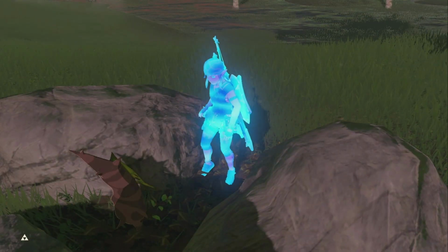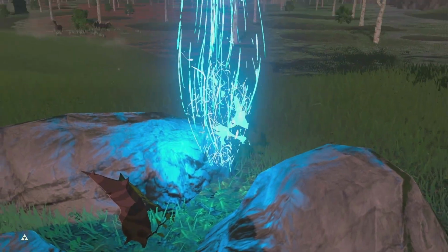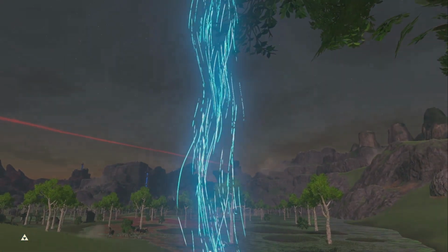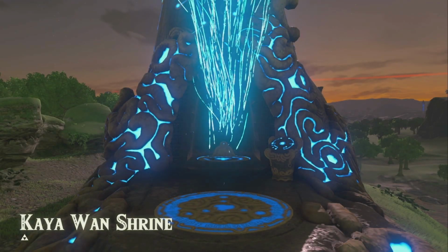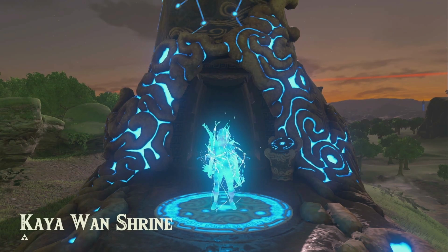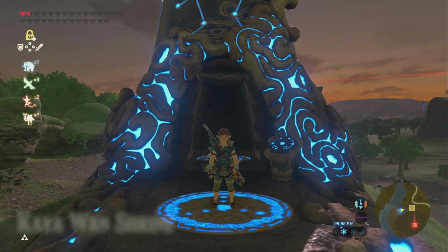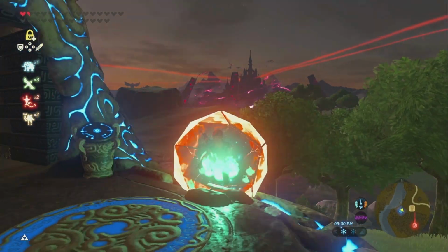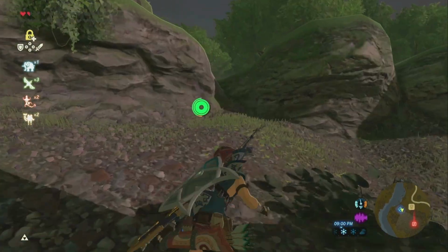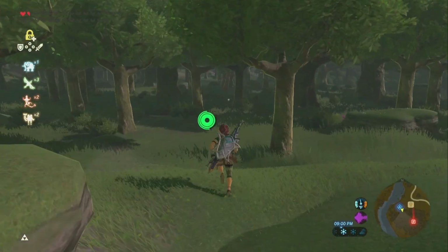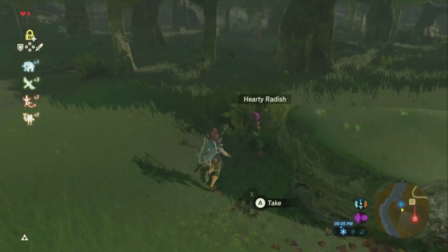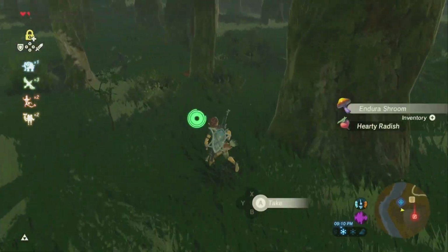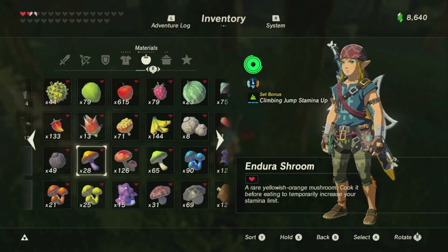Strategy. Look for leaks around the water heater and at the top and bottom. Be careful with gas-fired water heaters. When the burner starts up, there will often be condensation in the combustion chamber running down through the center of the water heater. You may hear or see water droplets at the bottom of the heater. Don't mistake this for leakage. The condensation will typically stop within 5 minutes of the burner starting.